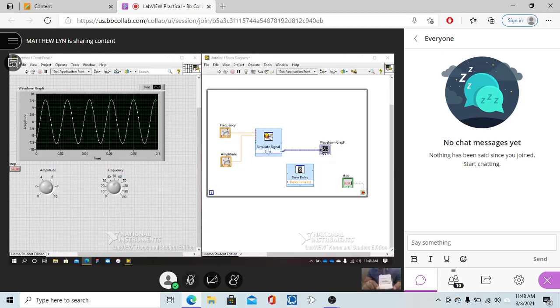So to configure a voltage measurement application, click on Analog Input, Voltage, and then click the plus sign next to the USB device and highlight channel AI0. So the first thing would be acquire signal. Acquire means input a signal to the DAQ that you want to display on LabVIEW.